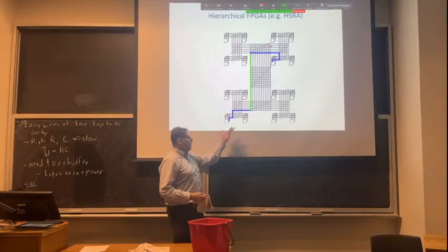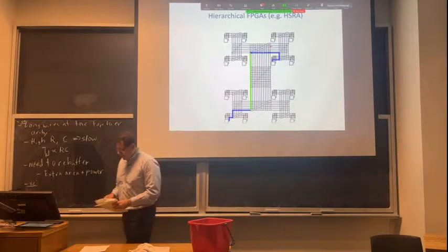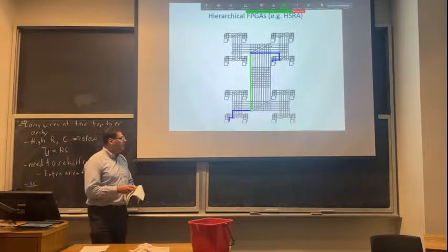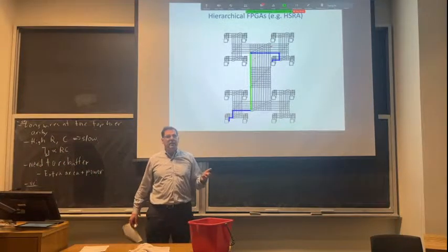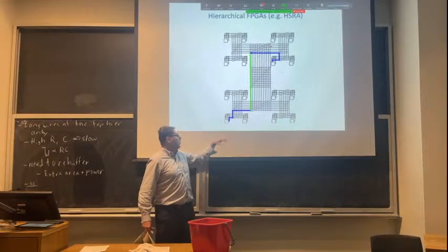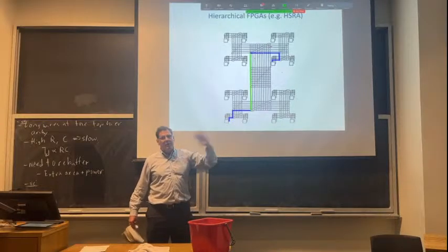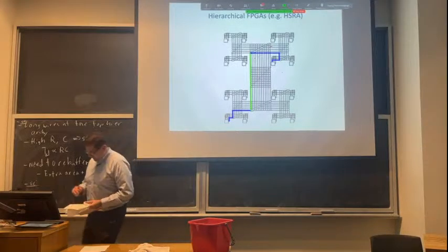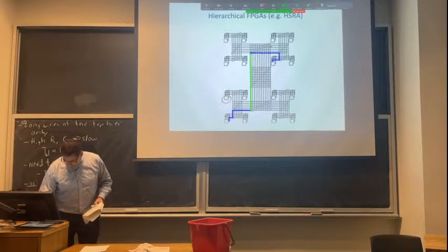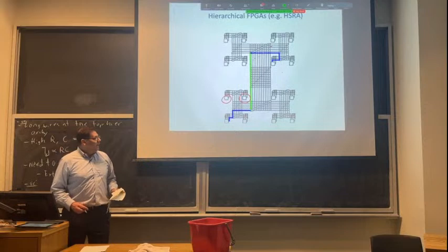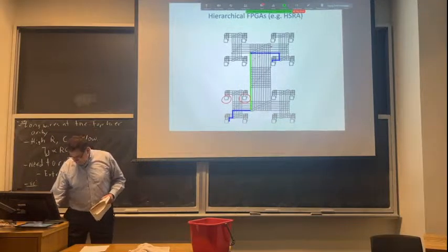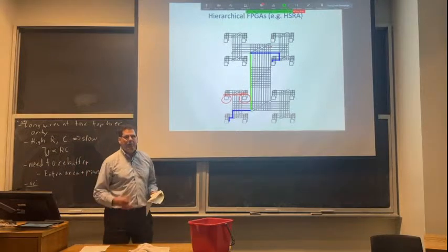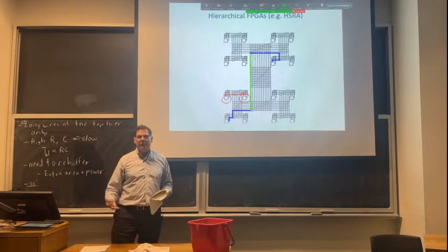It's kind of related. So basically, fundamentally on modern chips, wiring dominates delay. So if we have a lot of wiring between things, it's going to be slow. So let's take these 2 blocks, this block and this block. I can connect those 2 blocks together with just a relatively short level 1 wire. Okay, so that's pretty good. Short wire, relatively fast, relatively low capacitance, low power, it's all good.